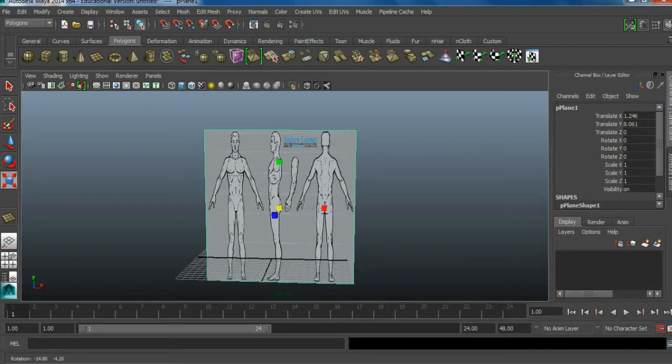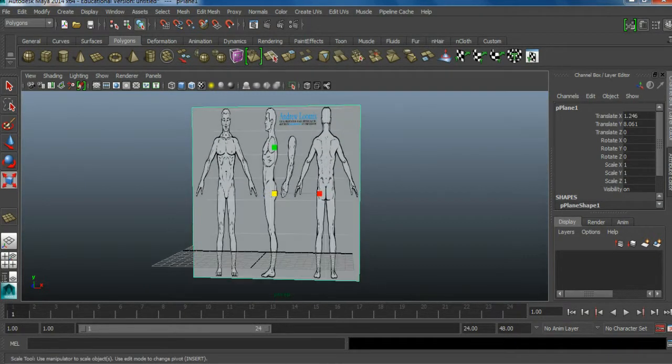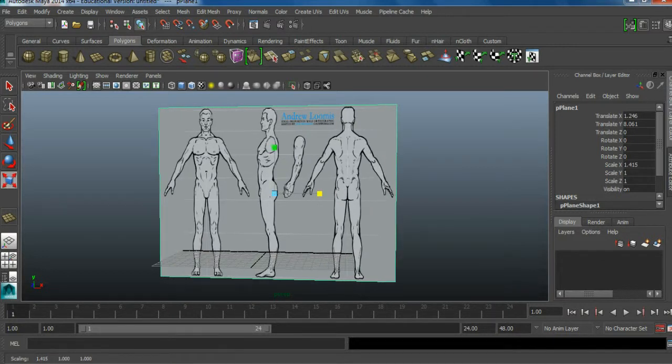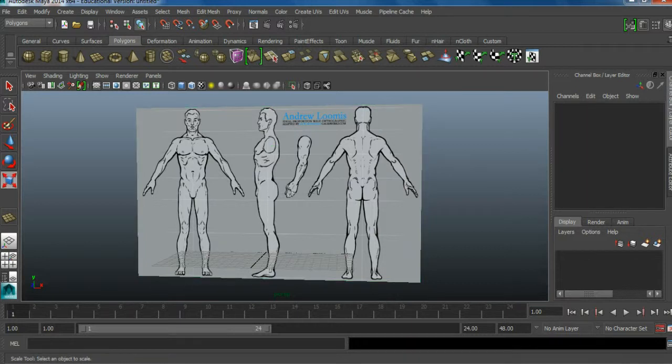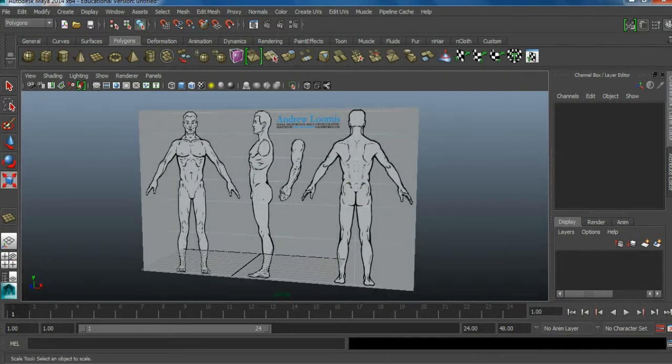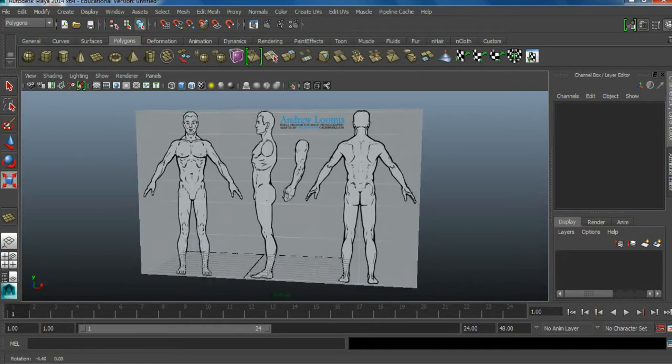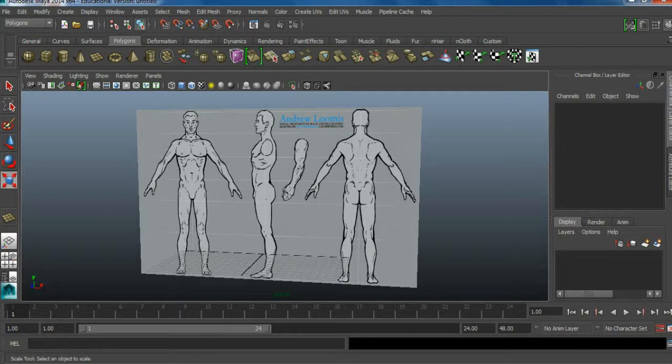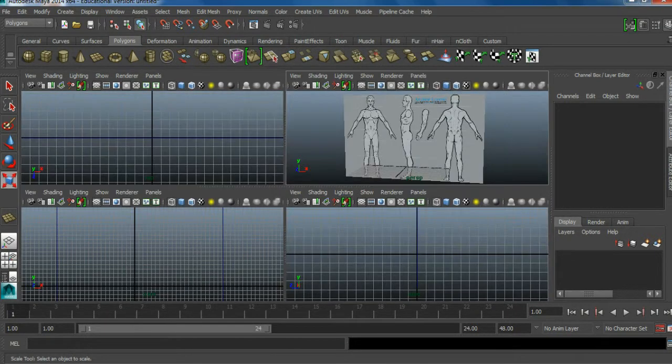Now if you check this image on my screen, it is a little bit squeezed because my screen aspect ratio is different compared to the Maya ratio. So what I will do is scale it a little bit in the x-axis, like 1.7. That was my screen aspect ratio, 1.73 or 77 or something else. It varies, so try to adjust it so that you get a decently proportioned image.